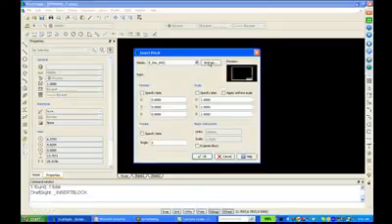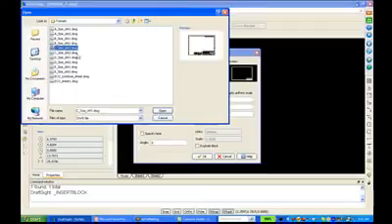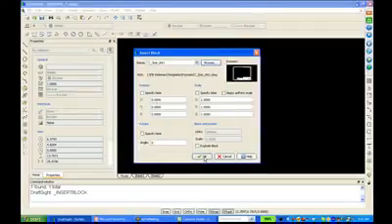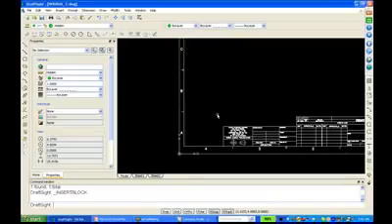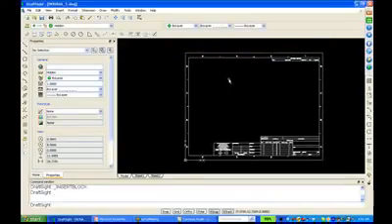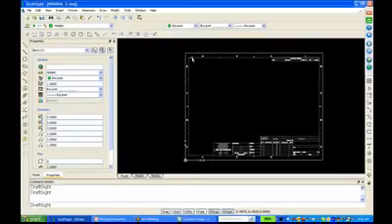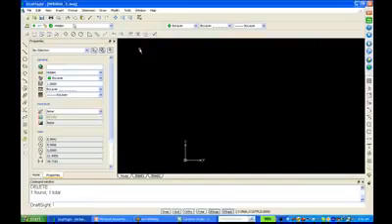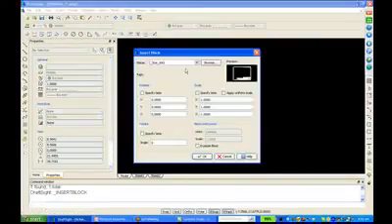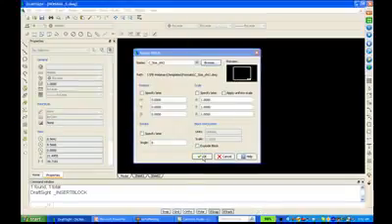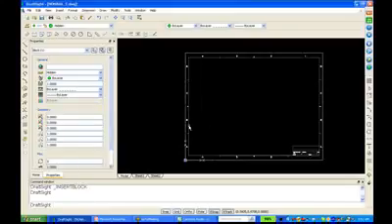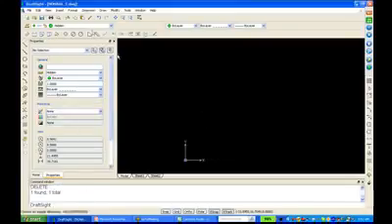This part of the webinar you probably can't do, but if you have drawings at your office, you can just insert those drawings, remove the geometry and the data that's in them, and then keep the border, and you can save it as a block inside your file. So I'm going to put in all these available drawing borders so that when I go to use my template file, they'll be there for me.